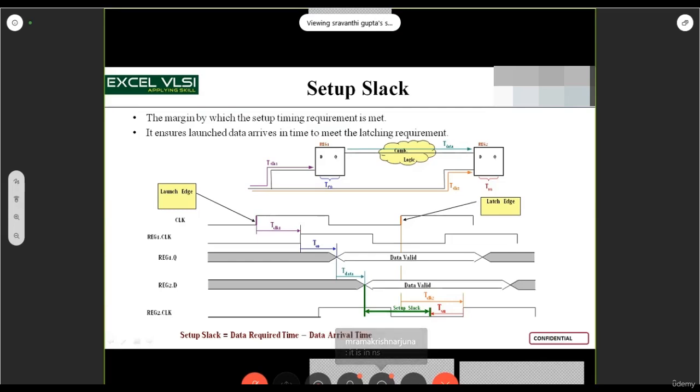Okay, it's in nanoseconds. 1000 nanoseconds is a huge margin. We can't have that much of a margin of positive slack. If it is 1000 picoseconds, then it's 1 nanosecond, which is fine. My positive slack might be that much, but 1000 nanoseconds is a huge margin. That much positive margin also we should not have as a slack value.